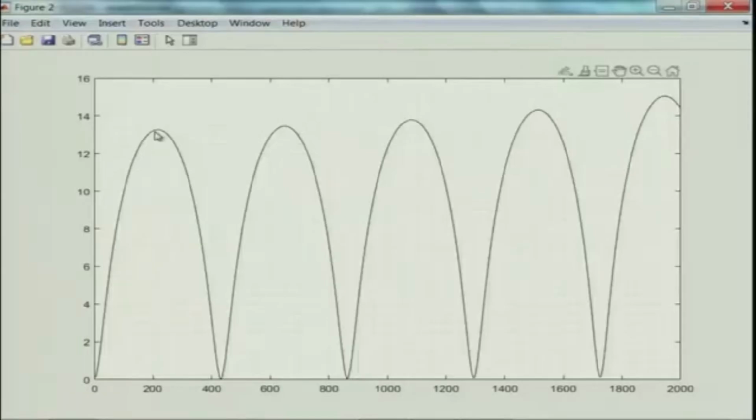You see, the maximum transmission loss follows the dome and trough pattern, exactly what you have for a simple expansion chamber. But do not be fooled into thinking, well, this looks just like a simple expansion chamber, so what is the use, why do this algebra. I have already told you the reasons why we must use a perforated thing and do some extra work in deriving the equations and getting the proper perforate impedance expressions. Although with this we would just get this, we will soon see how the extensions can dramatically affect and enhance the performance, exactly like we saw for the extensions without any perforate.